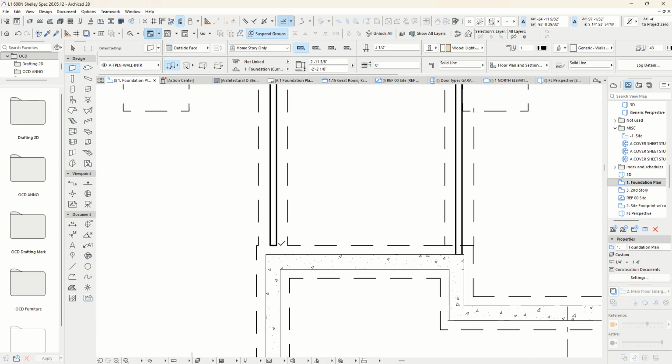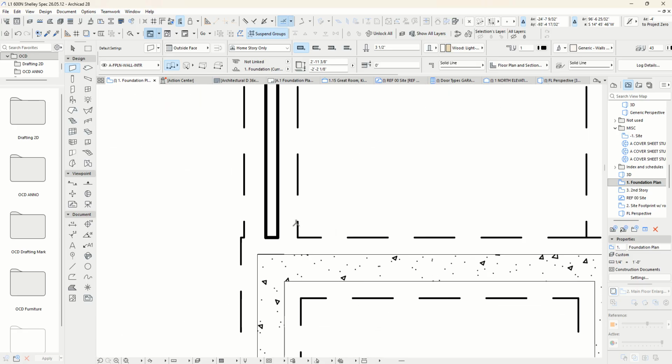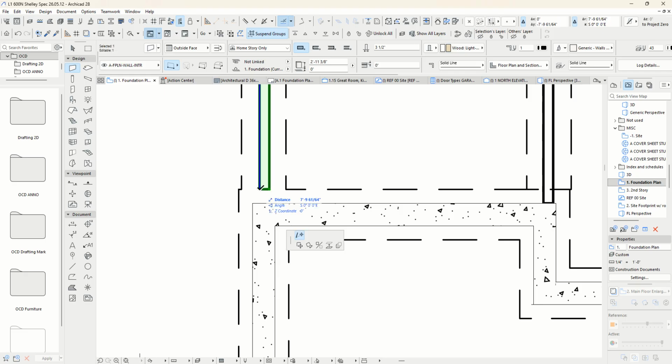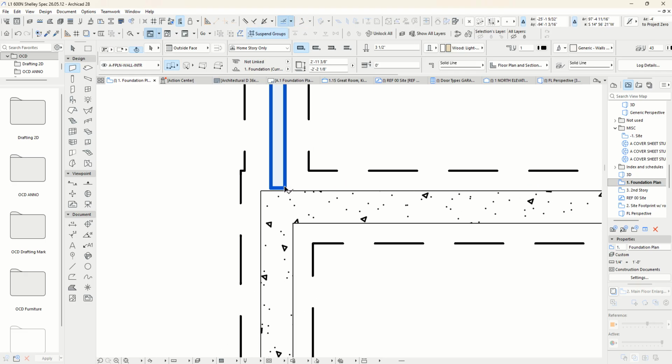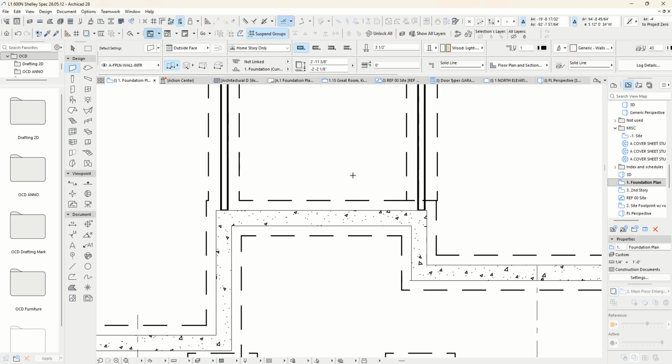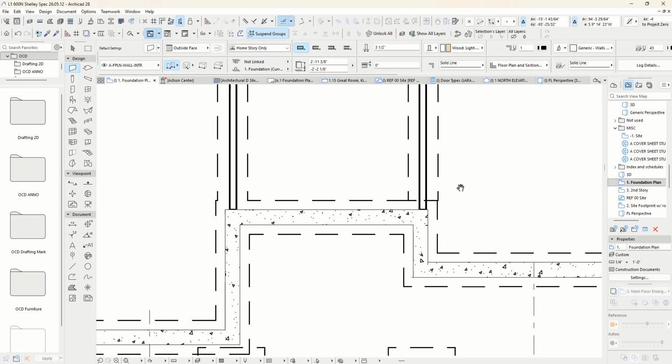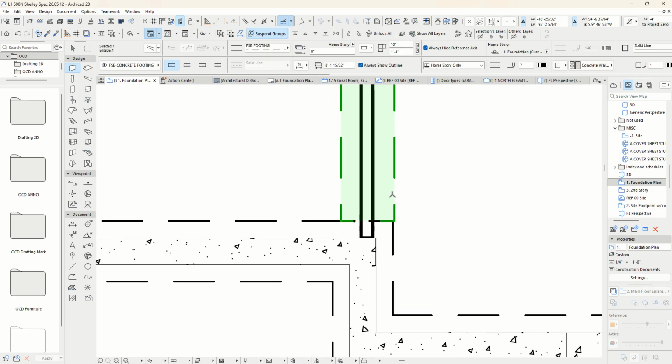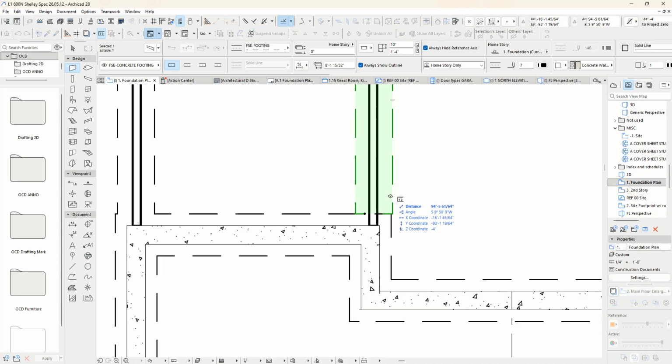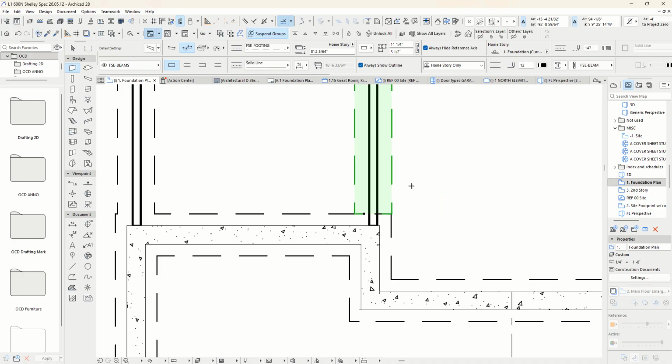When we've got something like this here, that looks fairly well centered. I'm not sure why that wall is so short, because a stem wall would usually go almost all the way to the wall. Sometimes if I put it there, it may merge and go right into the wall. This is what I got lost on before. There again, it's all about reference lines and offsets. So here I can see that this is not quite centered on that wall. Yeah, I've got 6.5 and 6. So there again, I got to move over 1/4 inch.